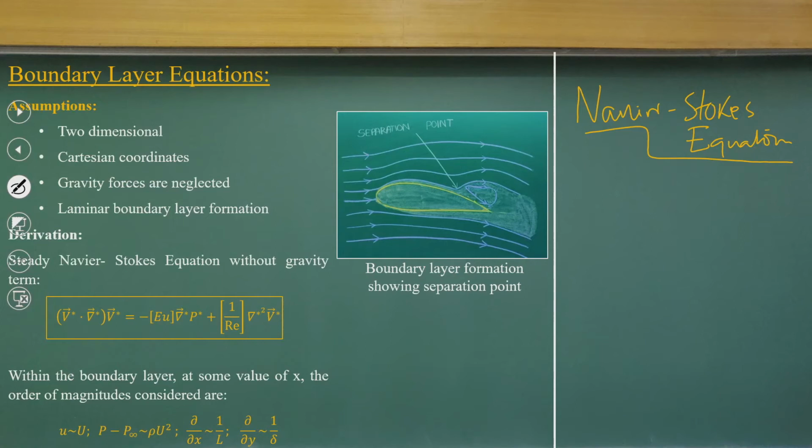So, for the basic equations, if it is steady, that means we do not have the local acceleration component. So, you will have the component of rho times the convective acceleration in vectorial form equal to minus grad p. If you remove the gravity component, gravity is neglected.